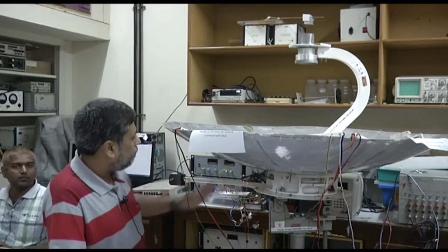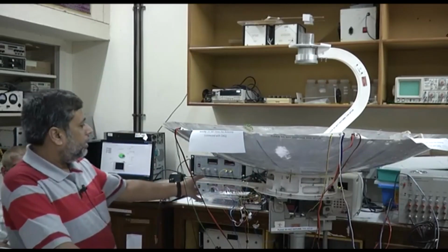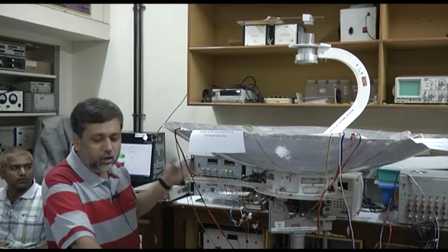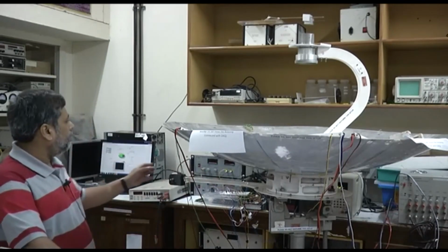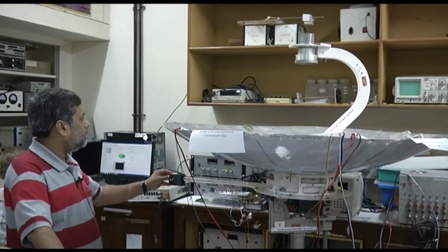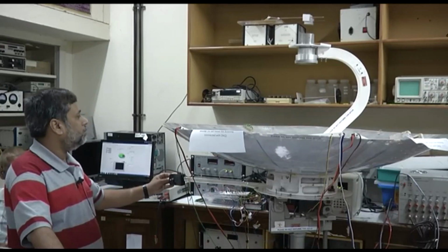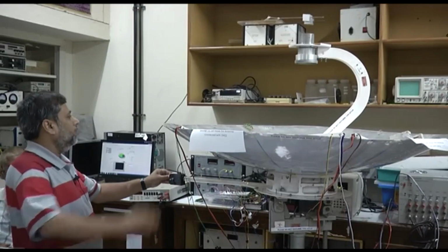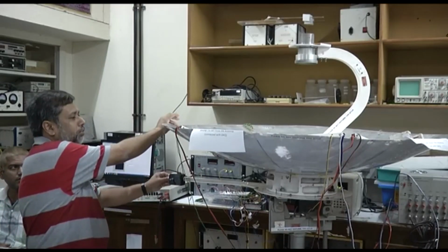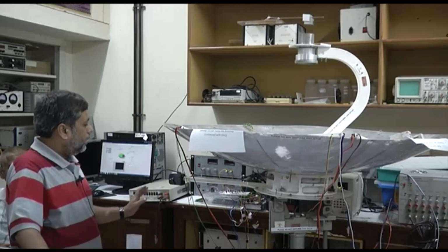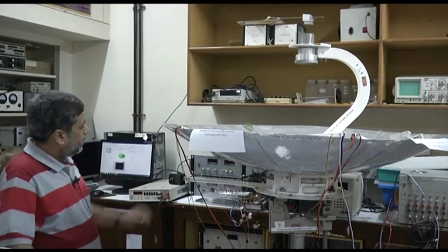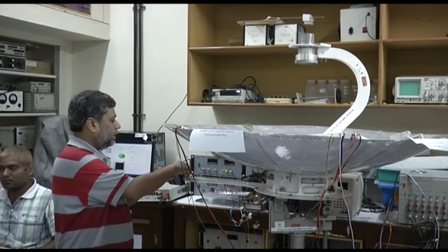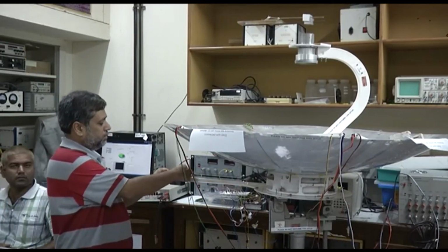Now the moment I apply the power, the SMA wire gets heated, that means it will go back to its memorized shape, and at that shape it is going to actually pull this system. And as it pulls, as you can see here, with every pull you are bringing this system down, so you are deforming it, and as soon as you get a desired deformed shape, you are going to lock it at that location with the help of this locking system.